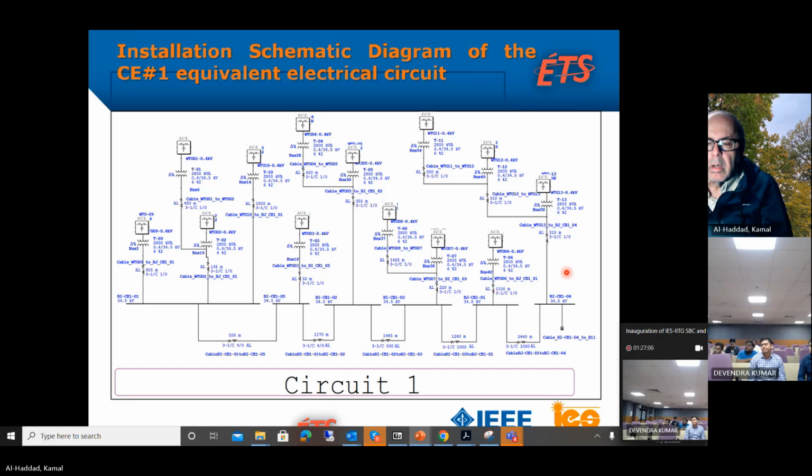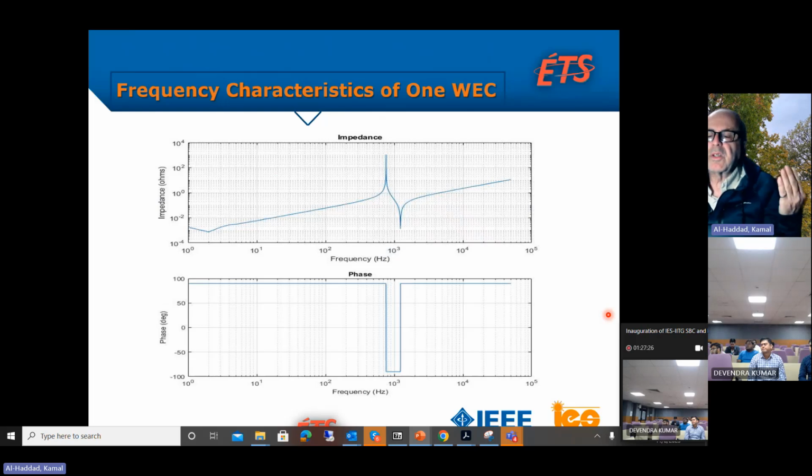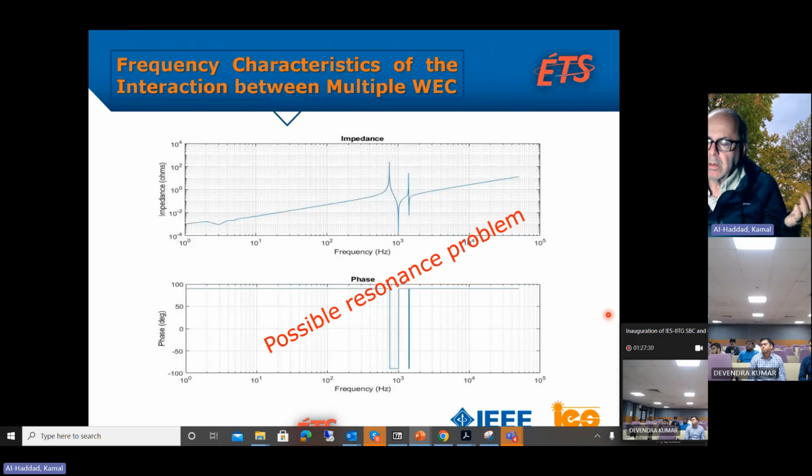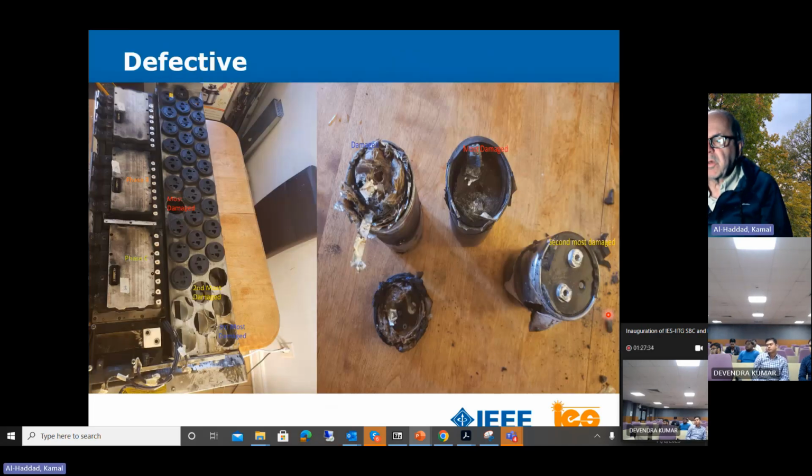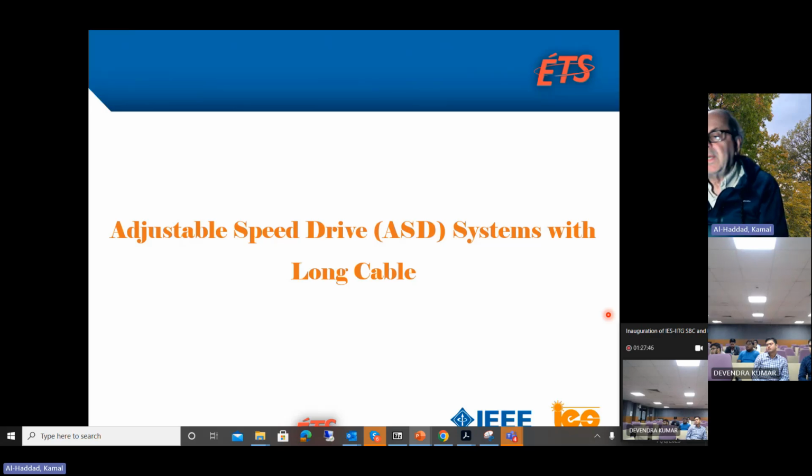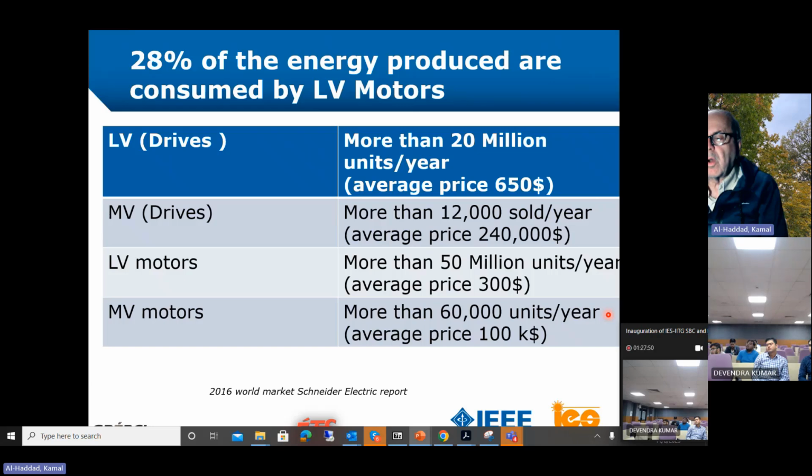Now this is a network; is this a stable network? The answer is no. Why? Because if I introduce any harmonics close to any resonant frequency of these branches, I will excite the circuit, and I will end up having resonance, and I will have thousands of amps circulating between the components, and I end up, which is most of the case, blowing up the converter and the filter that is used in those wind turbines. So what is the problem? We need to have a solution where there is no filter whatsoever. We need to remove those filters, and bring all these back to first order type of load instead of having them higher order type of load.